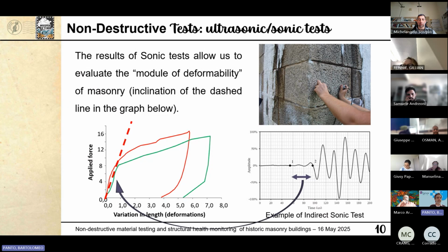However, since in the literature there are many empirical relationships between the elasticity characteristics of the masonry and, for instance, the ultimate strength, we can get help from this literature. So even if the information is partial, it is very, very helpful to calibrate our model.